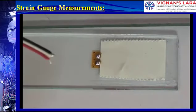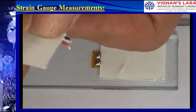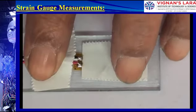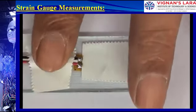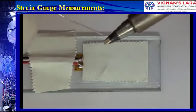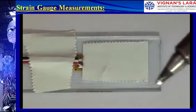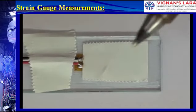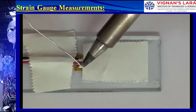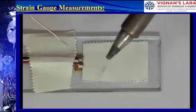The lead wires are positioned over the gauge tabs and held in place with a short length of PDT-2 tape. The lead wire is then heated with the tip of the soldering pencil, and a little fresh solder is fed into the joint before lifting the pencil away. This is repeated for the second lead wire.